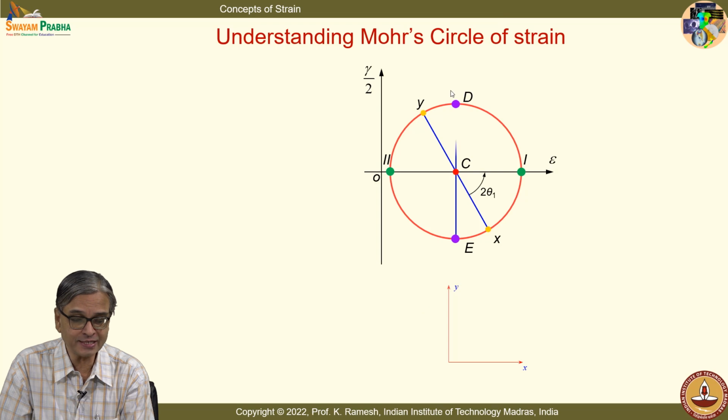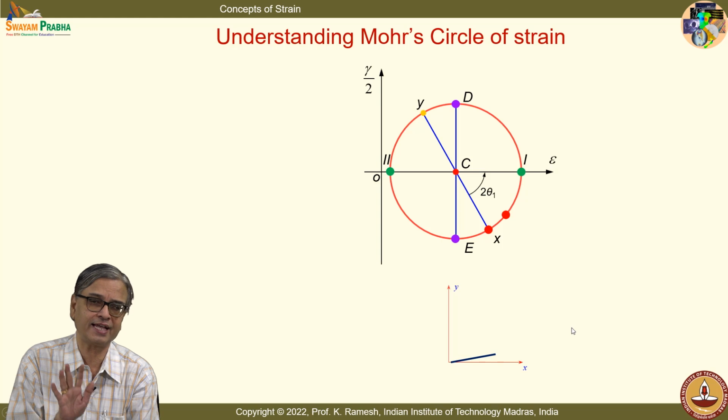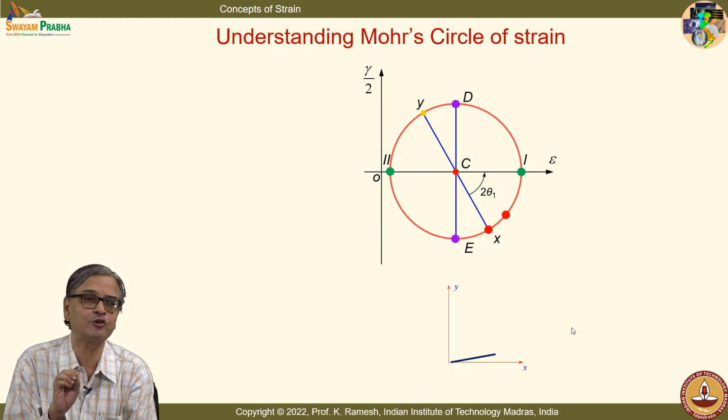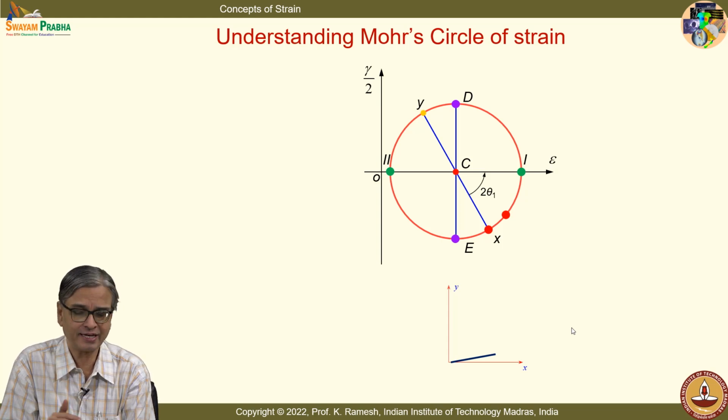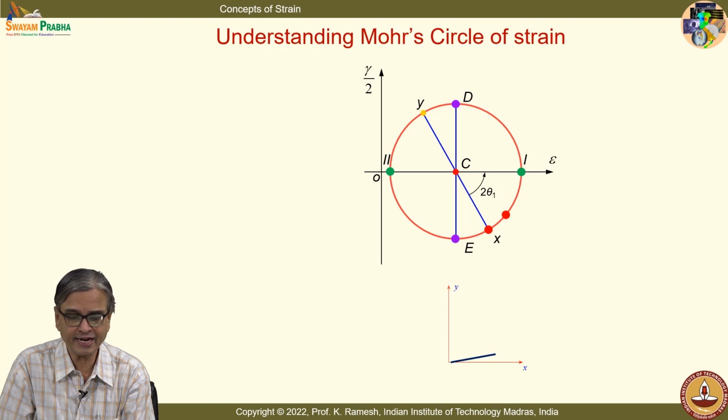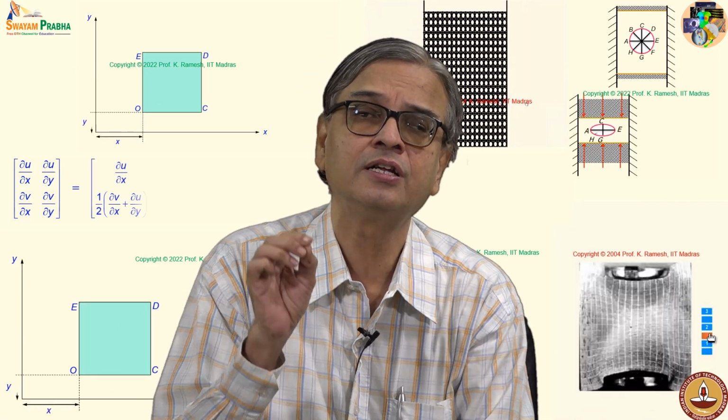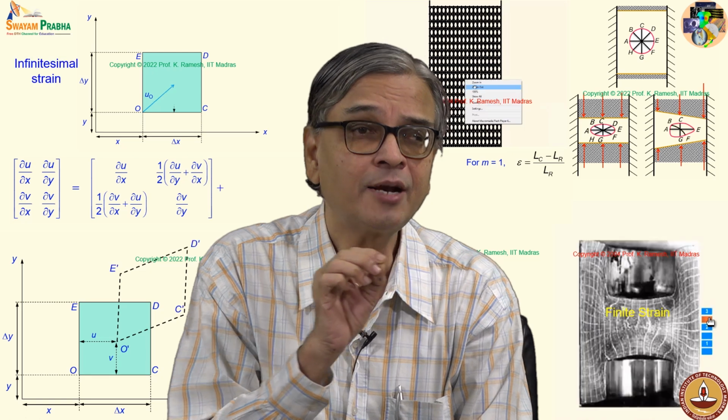And I can also express as components along the shear directions, maximum shear direction, here it is a local maximum. And if you take any point, that represents strain in a particular direction. See, I have just shown the direction, I have not taken effort to show the change in the length, which I was able to do easily in the case of stress, but here it is too difficult to do. So, what is indicated here is when I go one full circle of 360 degrees, I will traverse 0 to 180 on the physical plane. So, every point denotes what is the strain in that particular direction.